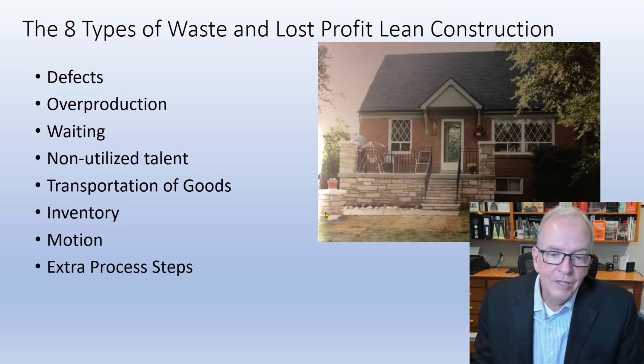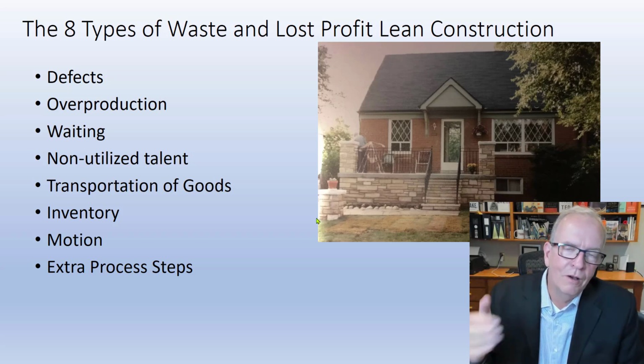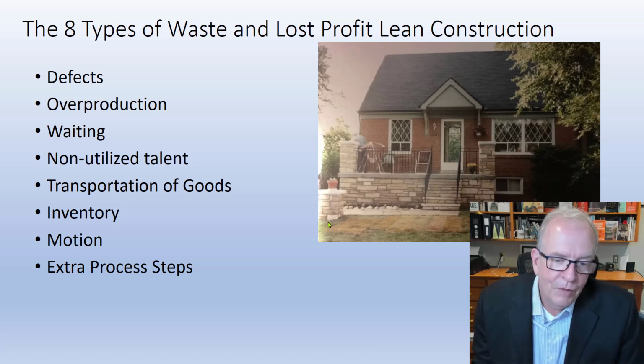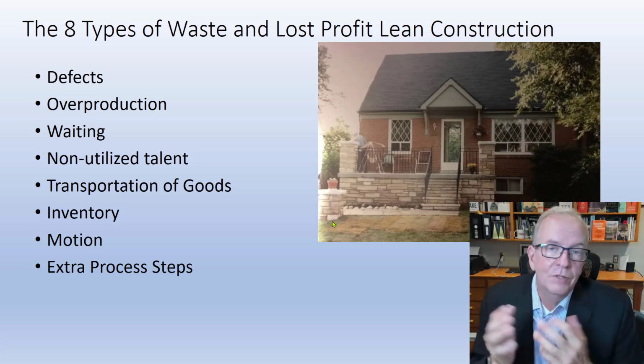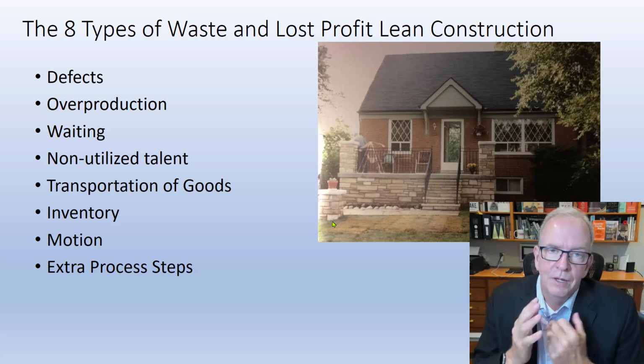It did last a long time, and it's still there. But because I dig around the earth, I could see a little bit of the bricks falling off over the years. If I had put the stone on top of the concrete, unless somebody hits it with a truck, it's going to last 60 years, 70 years, easy. It's been about 30 something, but it is starting to deteriorate down there. So that was another defect that was easily resolved. Even if I used a concrete brick, it would have been fine, but not a clay brick.